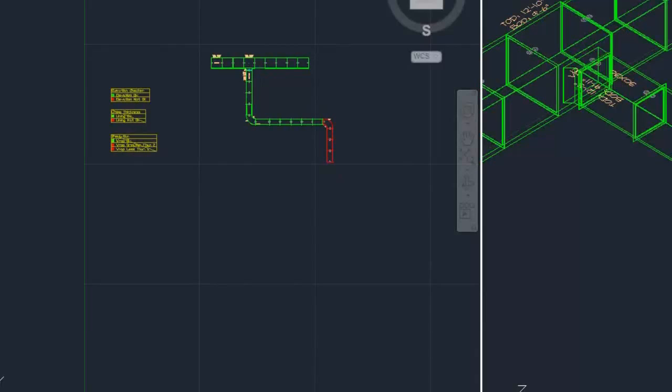So if you happen to use the software to do some design work and you actually set the CFM values on the duct, you can create a display theme to show the different CFM values. Again, anything that you can imagine and create in a property set, you can apply a display theme for.